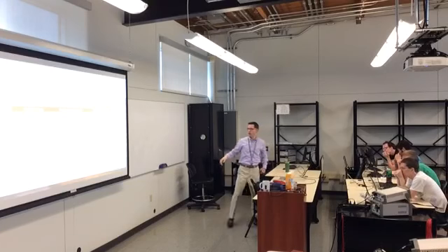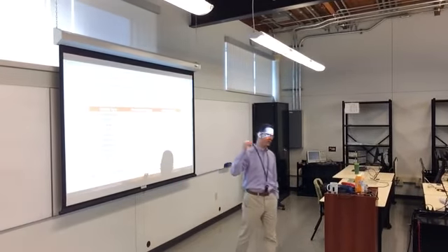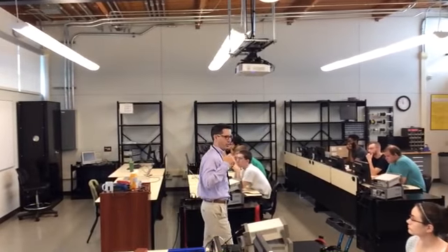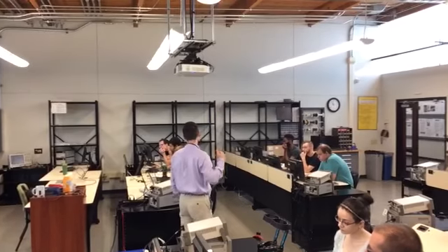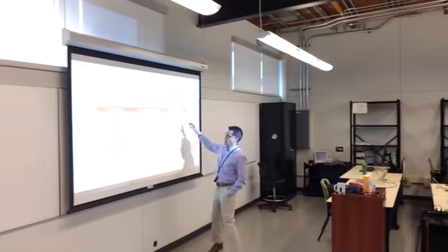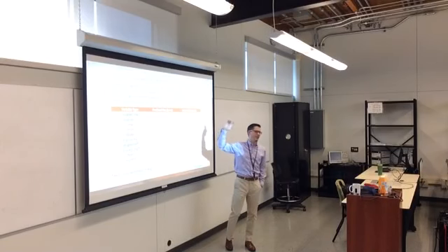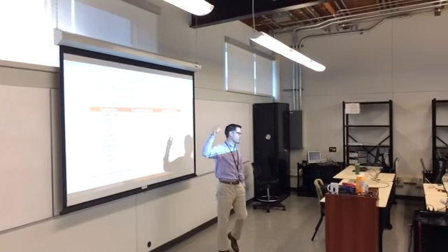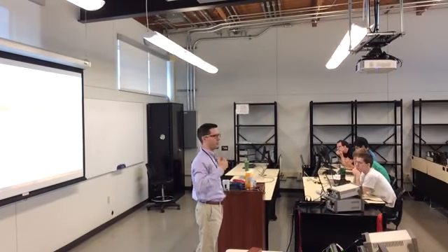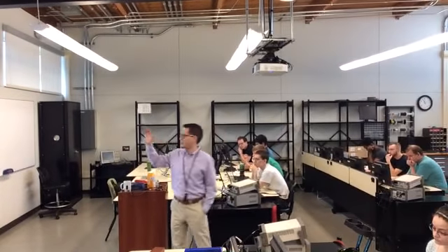Your variable sizes. It is a 32-bit system. So that means that generally all of your variables are going to be 4 bytes long. So an unsigned int, a long, a float. A char, an unsigned char is usually a byte. So you'll see in a lot of embedded systems, people will use unsigned char in place of a byte. You're not always guaranteed that that's how they implement it, but an unsigned char is usually a single byte.